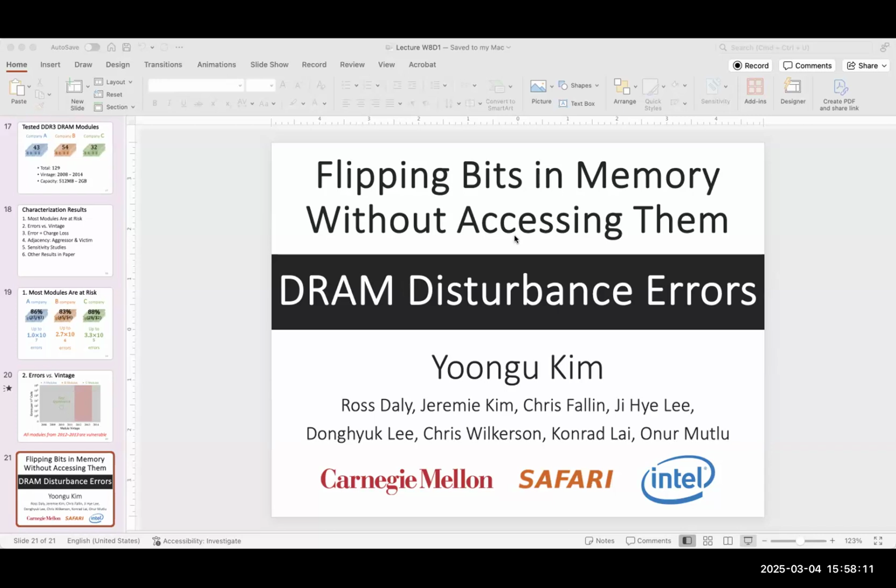So in our example, the noise margin is 0.5, which basically means that even if we have a disturbance within 0.5 volt, our signal will still be interpreted correctly in logical terms, right? And is everyone clear on this? So this is a VOH of 3 volt, voltage input high 2.5. So this is your noise margin high.